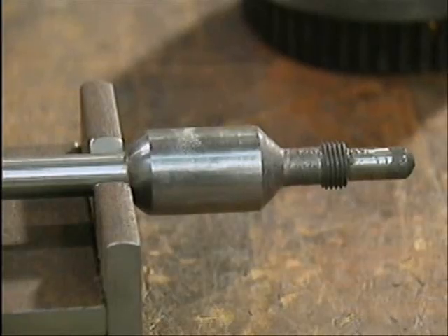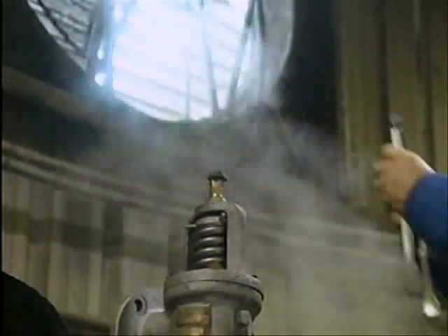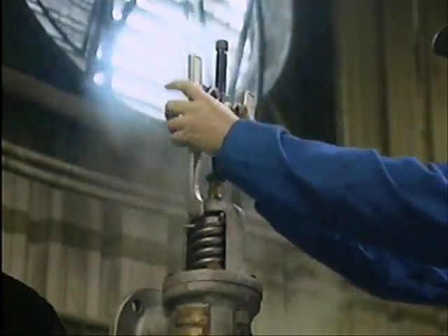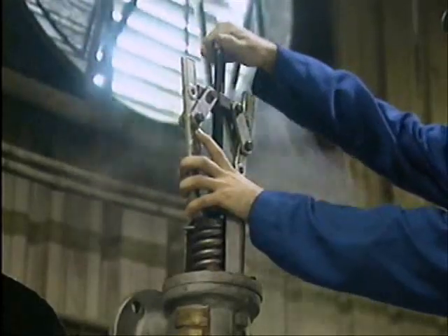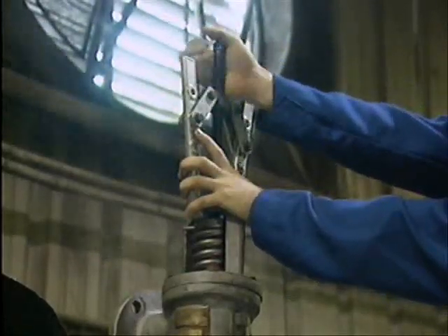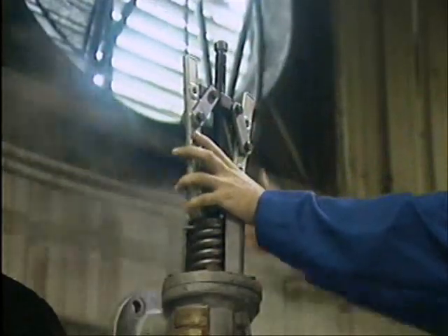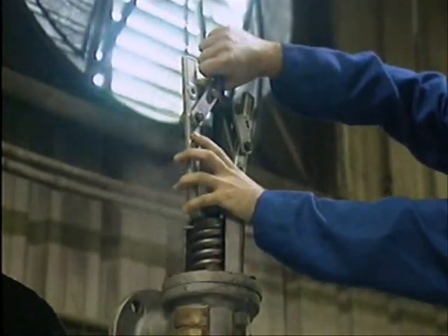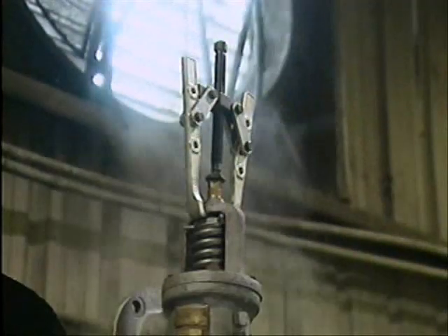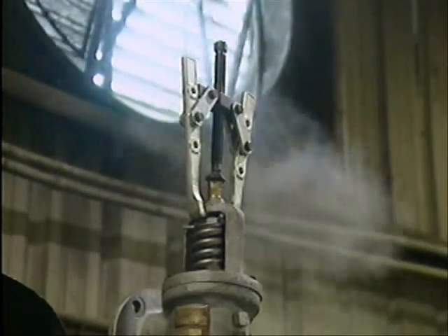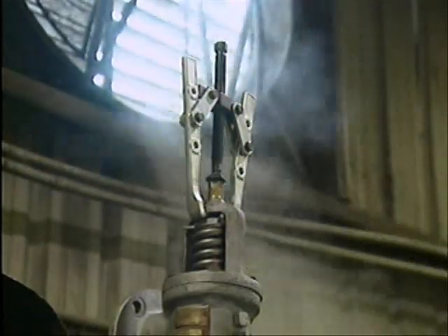Two common causes of bent valve stems are careless handling and improper gagging. Gagging is the act of attaching a device called a gag to a safety valve to keep the valve from opening. Gagging is usually a preparation for the testing that's done before a reassembled valve is returned to service. Proper gagging procedures are covered in the part of this topic that's entitled Reassembly and Testing.